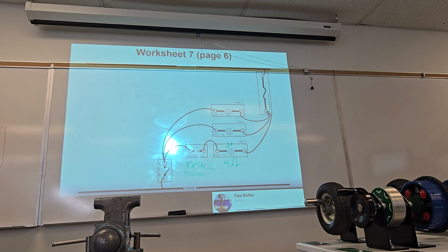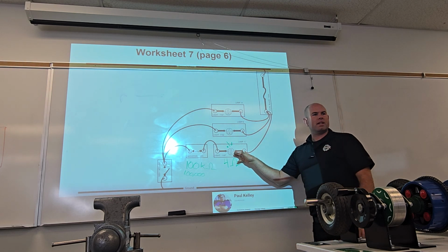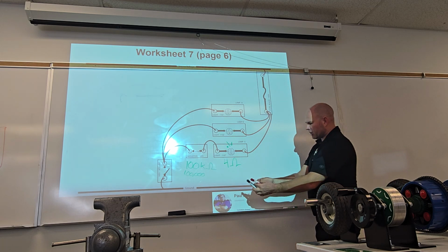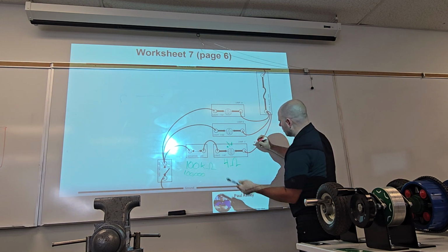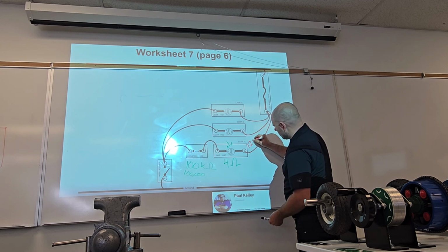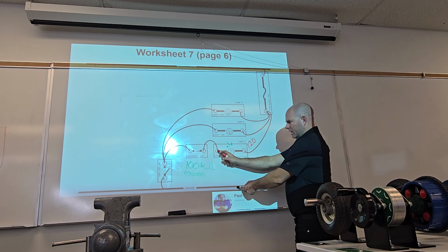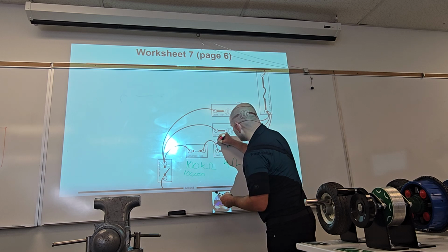Okay, now we're troubleshooting a problem car. I have a brake light working, a brake light working, a brake light not working. If I were diagnosing, I'd take my black lead, put it on the ground, take my red lead, and I get a 12.0. Cool. And then I put it here, and you know what I get? Tell me. Technically not 12 anymore, though, but yeah, exactly, 11.9.